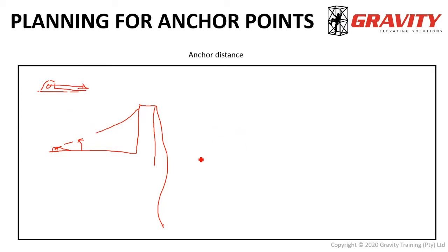However, if you use that same anchor point and you place it very close to this parapet wall, say there, and you rig your ropes, you're now pulling that anchor point straight up again, okay, which is not ideal for certain anchors. Again, the gravity axis hanger, this doesn't apply, but the more common, the standard anchors do have this problem.